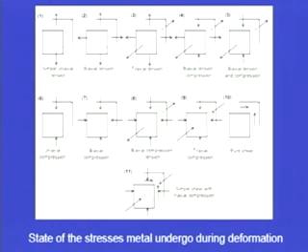Whenever we apply a compressive force to a rod-like specimen, if the slenderness ratio or the aspect ratio is not suitable, then it will buckle under the applied compressive loads. So, buckling will be the limiting factor for compressive loads and necking will be the limiting factor for deformation under tensile loads. Either the material will fail after the necking or after the buckling.